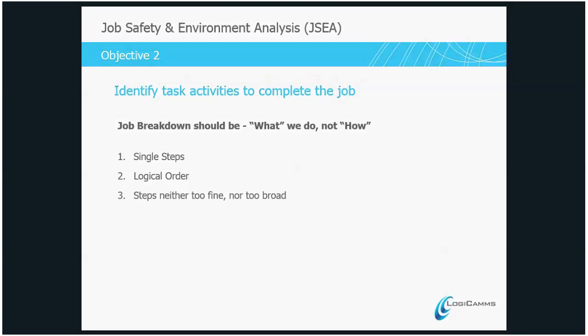And for each of these steps, say for traffic management, we can now put in the control: bund the work area and put up signage. Access and egress, we can say we will erect scaffold or put in a ladder. For other work groups, we can communicate, and identify conflicting activities or hazardous environment created before we position the digger.